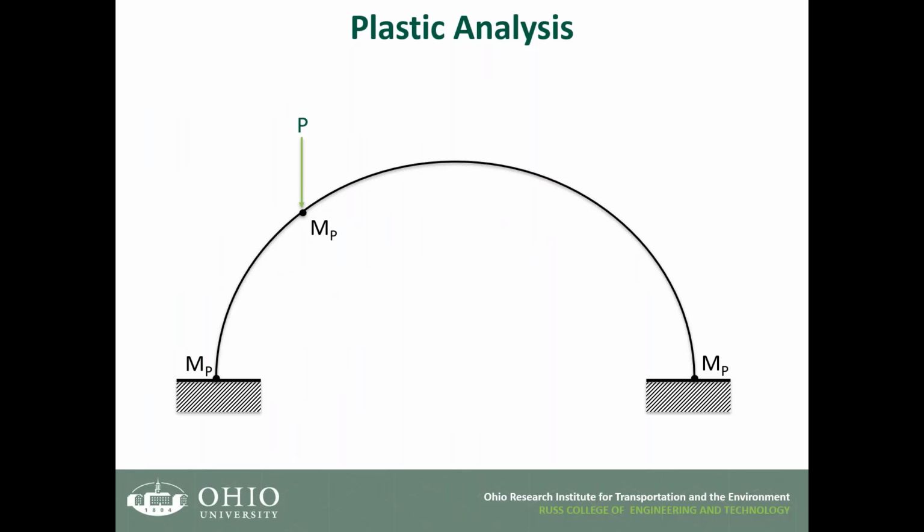You don't have to even include the thrust. But if it's above that, then the moment and thrust have to be lumped together. Those equations that I showed you give the interaction between the plastic moment MP and the thrust. So if the thrust is very small, you ignore it, but if it's not, then you have to take the interaction between them. And that's the one that Kevin will explain.